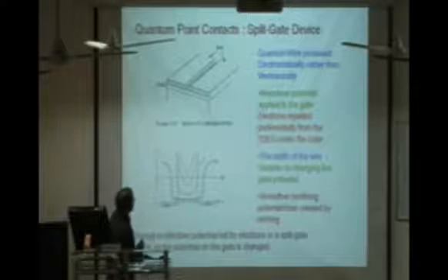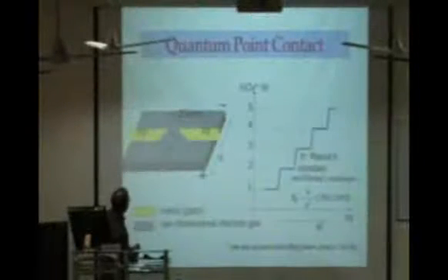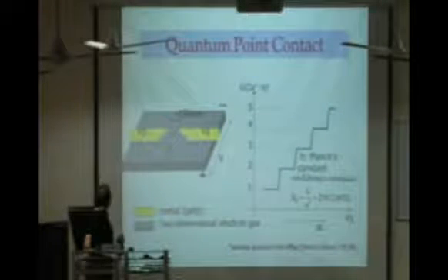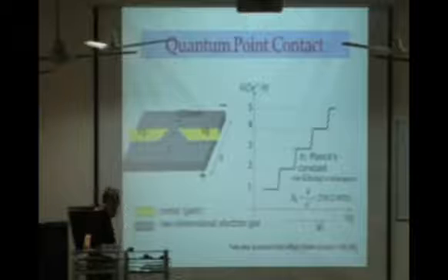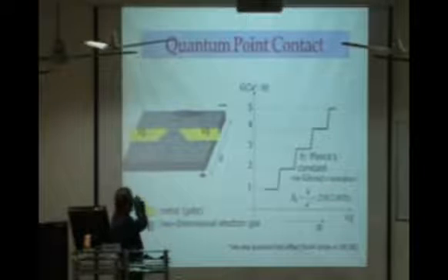So this is called a quantum point contact device. In fact, people have already demonstrated by electron beam lithography that if you make a MOSFET with a two-dimensional electron gas, and put two gates very close to each other, with a difference of about 250 nanometer in this case, which could be achieved easily by electron beam lithography.